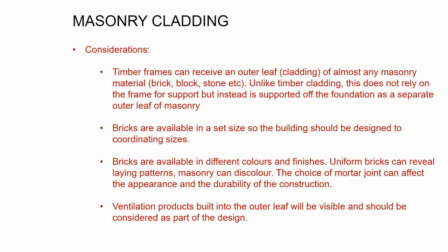So if we move on to masonry cladding, timber frames can have many different types of masonry cladding. We can use almost any masonry material, but most commonly it's brick or blockwork or stonework. And in contrast to timber cladding, it's not relying on the frame for support. It's supported off the foundation. It's got its own separate leaf of masonry.